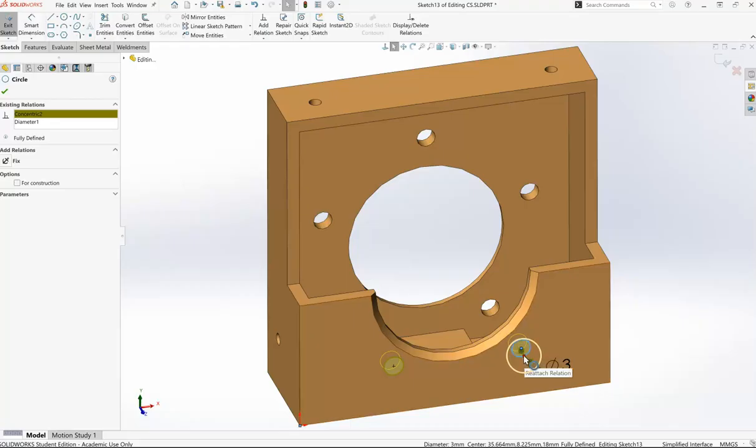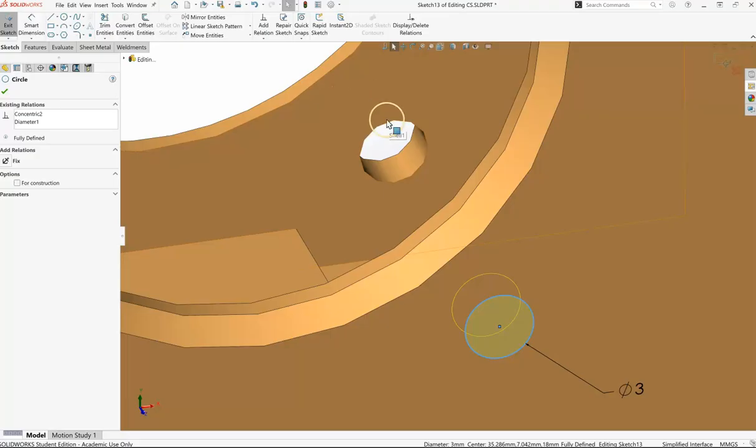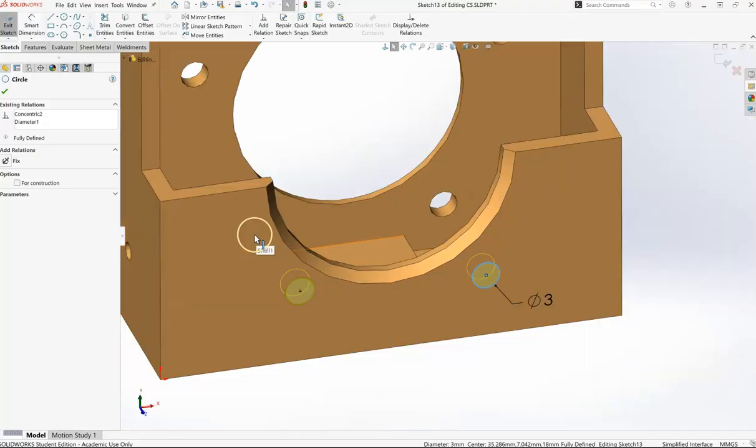And so again, I've got this little red drag handle, and I should be able to take this handle and drag this back and make that concentric again with that circle, and it did. It took the color off that concentric circle.